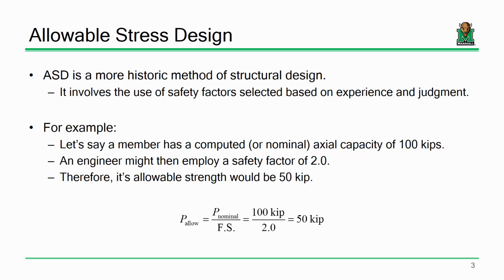It's pretty tough to come up with a calibrated design philosophy for something like geotech. Anybody who's got any experience in geotech will tell you that if you go drill right here and go drill over there, you're going to get different soil properties. It's going to happen, okay? So you're going to have to, I don't want to say wing it, but at some point you've got to just go with a factor of safety that makes sense, okay? And there's judgment that goes into that.